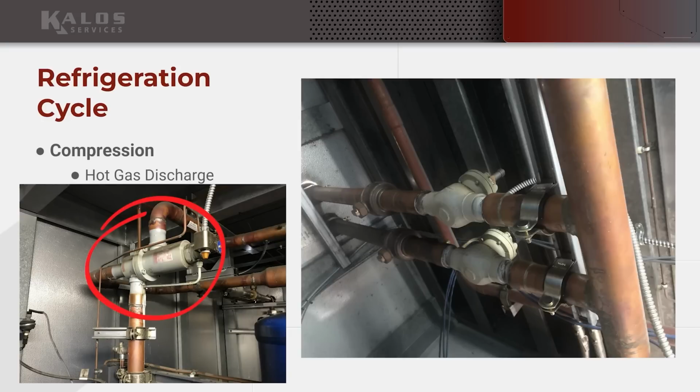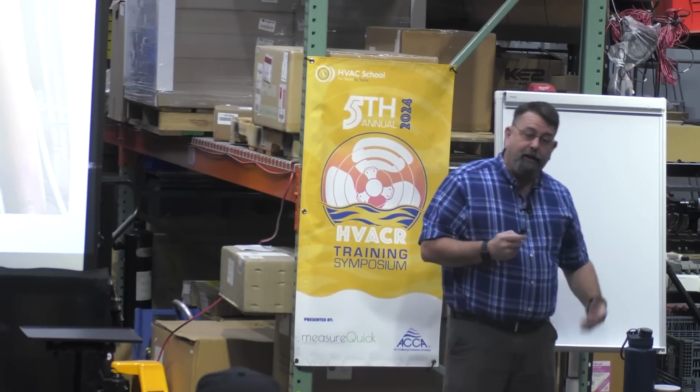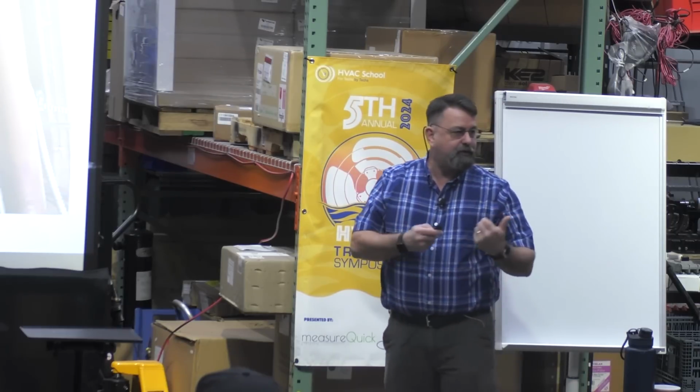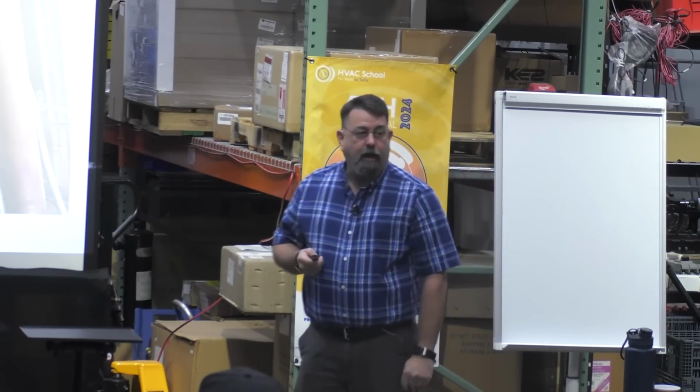I'm not using it, right? Well, this three-way valve is going to give me an opportunity to actually use it. If there's somewhere that I need heat, I'm going to use a three-way valve and make that heat go there instead of just rejecting it outside when I need it, right? I might not always need it, so that's why I've got a three-way valve there, so I can kick it back and not use it when not necessary.